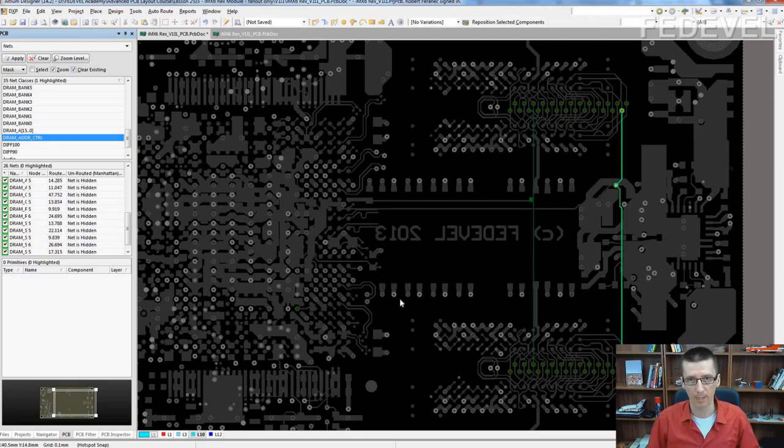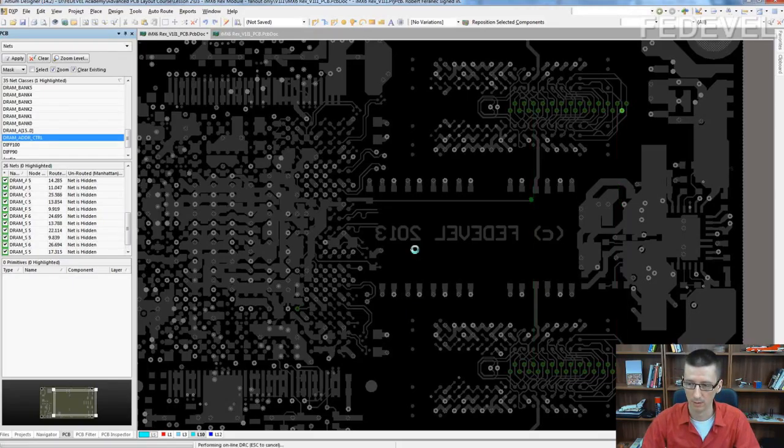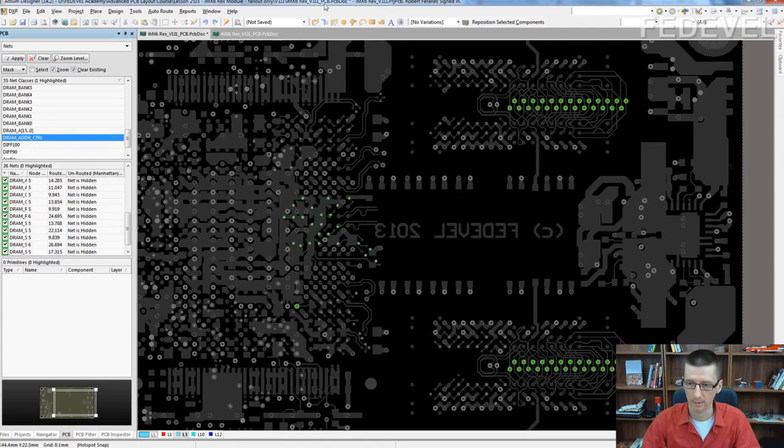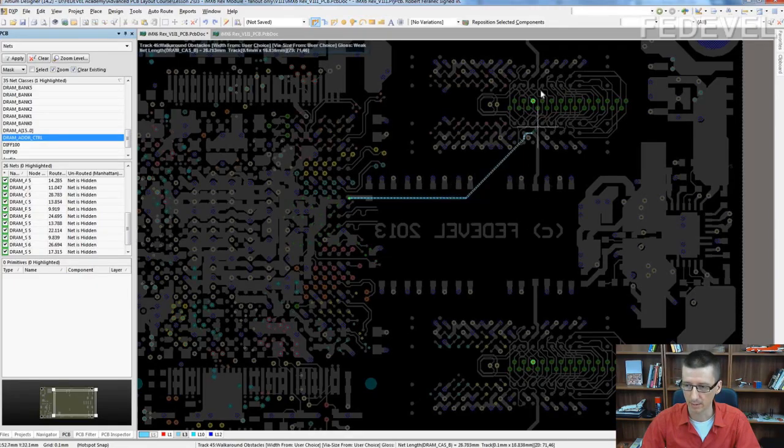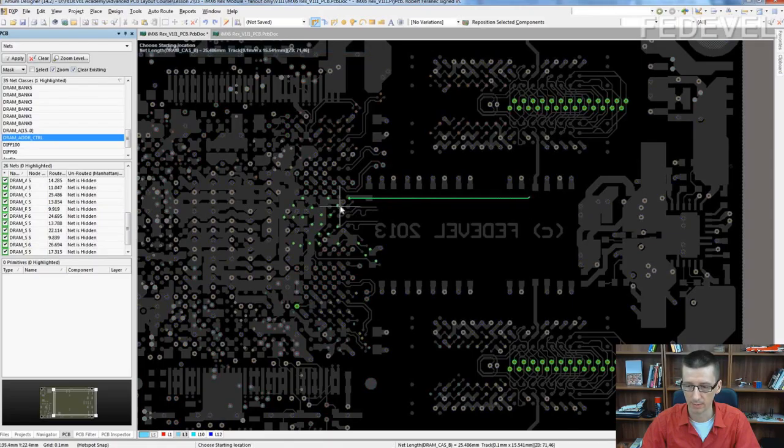I do the layout partially, do some area, connect them together. I will show you. Go on layer 3, highlight, just very simply draw a track to the position where the via needs to be placed.